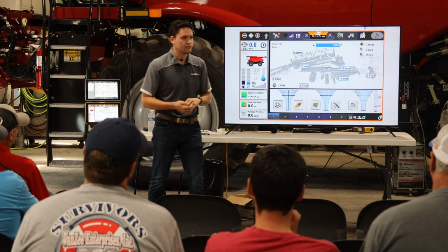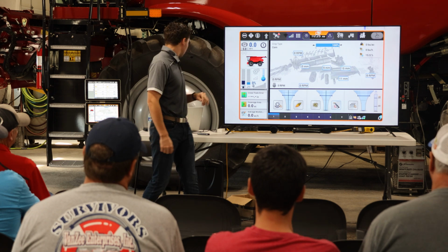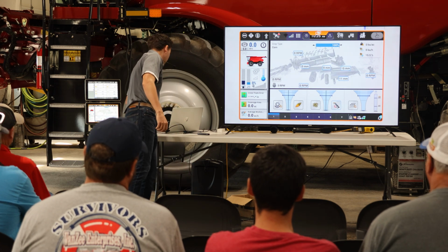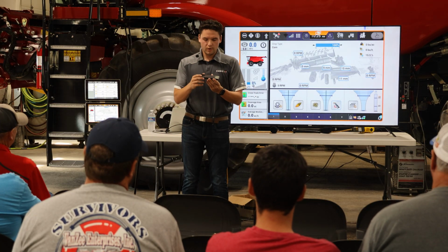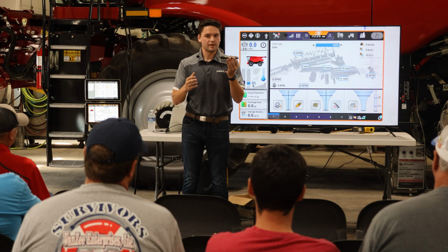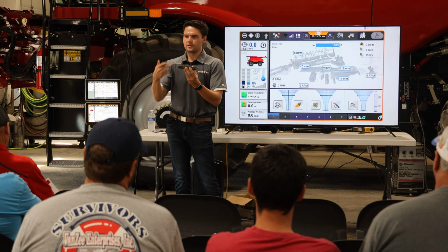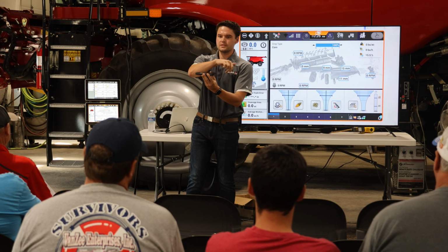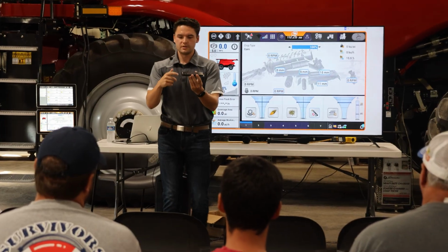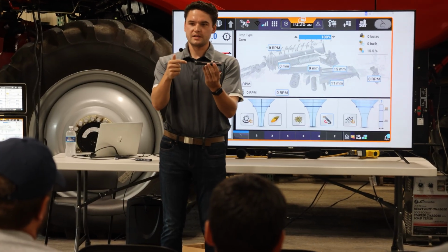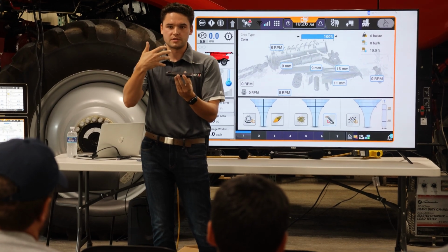What's new with the 250s and now 260 automations? So let's use my phone here as an example. Let's say that we're going along, and this is my upper sieve. At the back right and the back left, above and below, there is an air intake. A single sensor here and a single sensor here. And all it's doing is measuring pressure differential, and that's how it's determining load. So there's an air intake with a sensor here measuring the airflow that's coming off of the cleaning fan through our sieve.